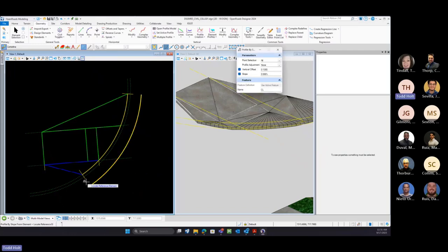So it's kind of backwards. I would probably start with my edge of pavement and use that as a reference and then for flow line for back top. And then I could project the slope off of this if that's constant down to 0.13. I'm just doing it backwards from flow line back to here.